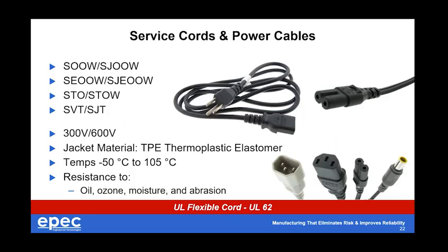We talked a little bit about service cords and power cords and how we can obtain UL on the finished product, but that's a lot easier if we're using an existing UL approved service cord. If you look around your house, maybe find an old extension cord, read what's printed along the perimeter of that wire jacket. The odds are you're going to see one of these classifications, whether it's SOOW, SJOOW,